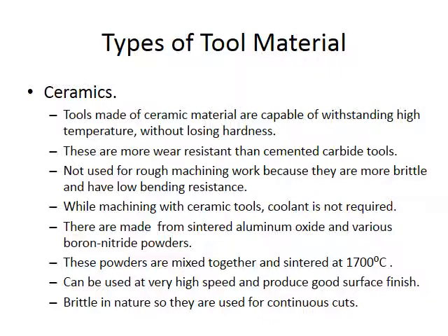Ceramic tools are made from ceramic material, capable of withstanding high temperature without losing hardness. The main concept is that these are more wear resistant than cemented carbide tools. They are not used for tough machining work because they are very hard but brittle and have low bending resistance. While machining with ceramic tools, coolant is not required at the time of cutting.